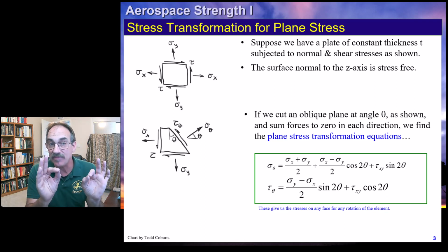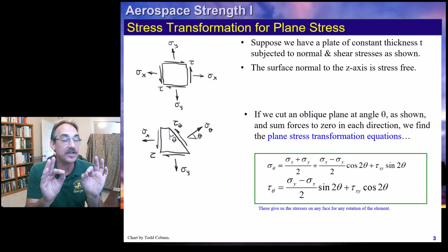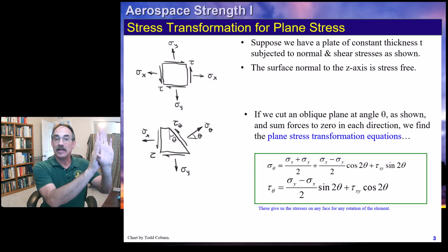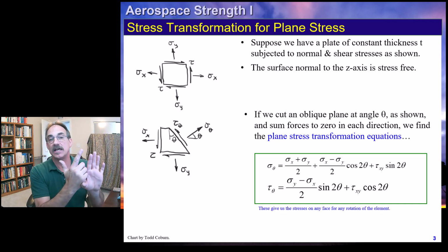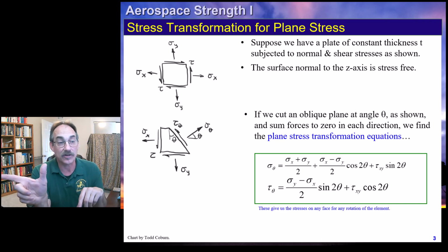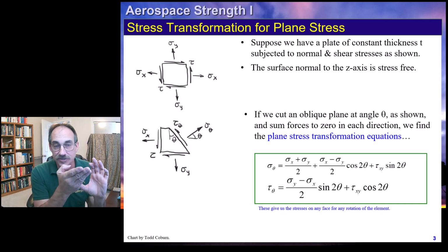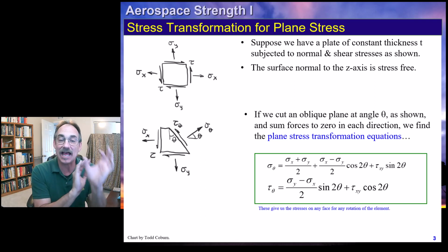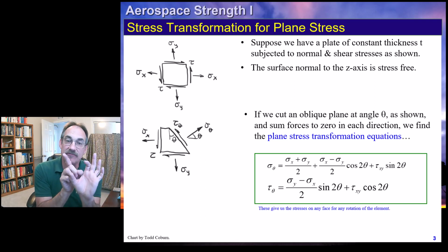We've got sigma theta, and all we need to do with our original element is define positive x and positive y. Even though I aligned this with a horizontal and vertical axis, we can use this transformation for any element we find. Just define a positive x and a positive y aligned with the way that element is oriented.